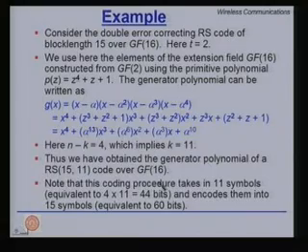Note that the coding procedure takes 11 symbols, not bits. So, it is (15, 11), but it is not dealing with bits, it is dealing with symbols. But we are over GF16, so each symbol is 4 bits. So, it takes in 44 bits and throws out 15 symbols, which is equivalent to 60 bits.